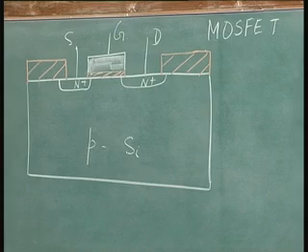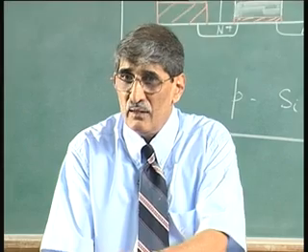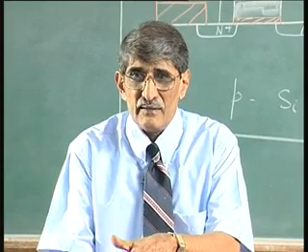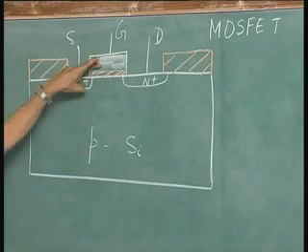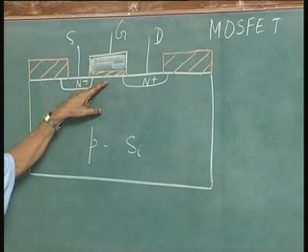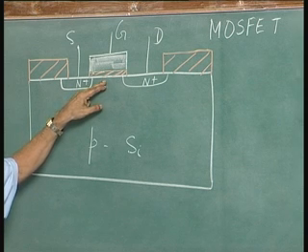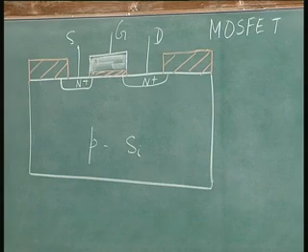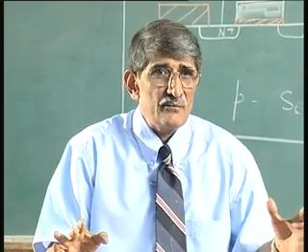What was conceived was you put an oxide, a dielectric material, they were trying germanium, put a dielectric material on that, put a metal gate on the top, then you must be able to control the region below that. By applying voltage between these two, you can control the region between them. For example, if you apply plus, you can deplete. You can apply minus, you can accumulate plus charges. That was the idea. But when they made the devices like that, it never worked. It never worked, not even a sign of current flow.